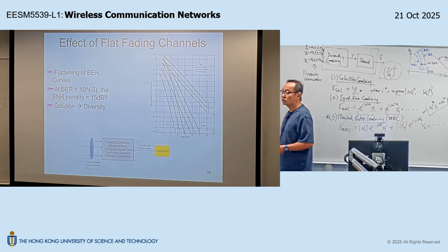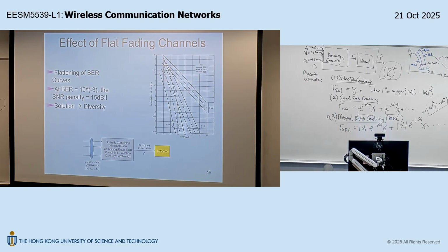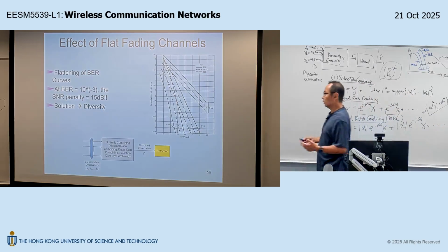So you want to design a chipset solution so that you can provide extended coverage for your access point, compared to your competitors. So you go through all the study, you know that you want to achieve two-order diversity. And for the reason I have explained, you want to have the two-order diversity coming from receive spatial diversity. So you have two receive antennas. With these two receive antennas, the first receive antenna picks up the first observation. The second receive antenna picks up a second observation, right?